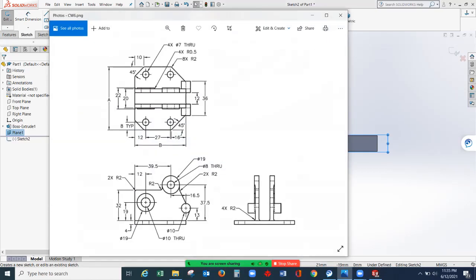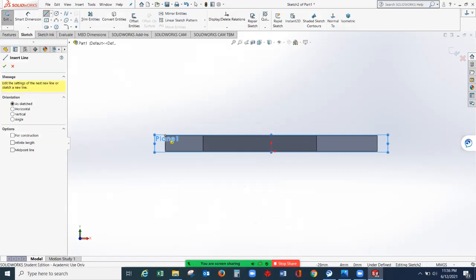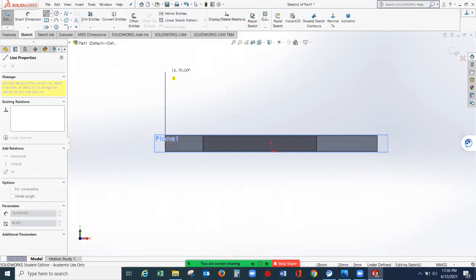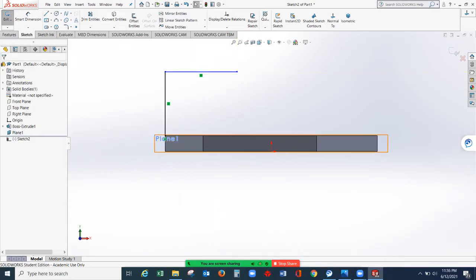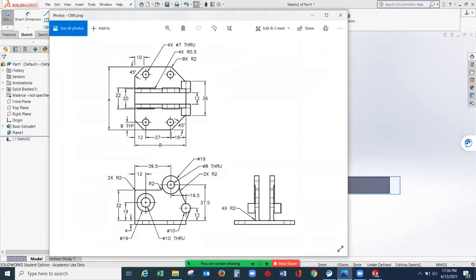Now take a look on this sketch. So from this sketch, I'm now on this view. Okay, so I will need to create this sketch from this view. So I have one vertical line and then horizontal and then one more vertical. So let's start with that drawing by creating a line. So line, I'll start from this point going up and then this point. So let's check the dimension first so that it will be easy for us to construct the other part of the drawing. So from here, you have 32 millimeters here